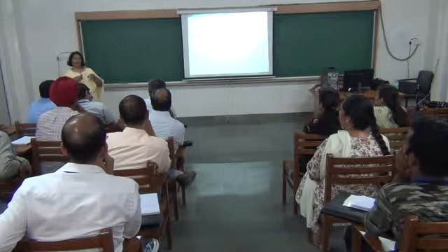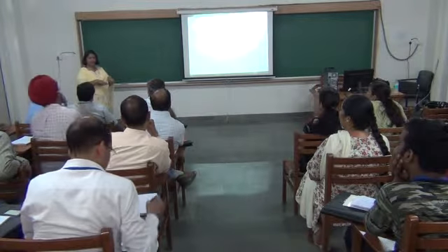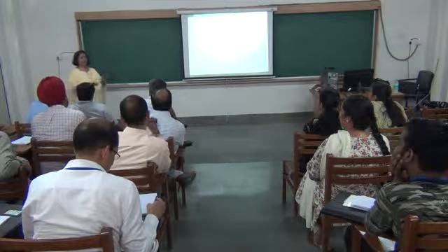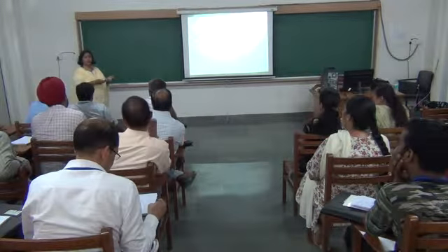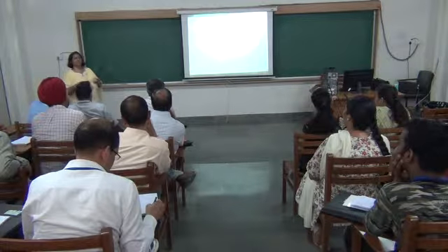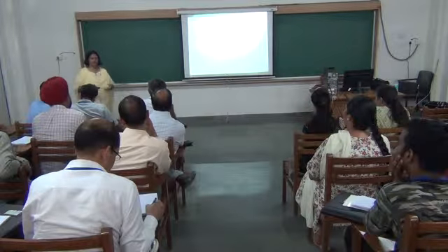And if I measure the voltage across R, it will go almost to 0. So it will be very difficult for me to compare one in millivolts or microvolts and the other in volts. So you should choose the frequency such that XC is of the order of R.